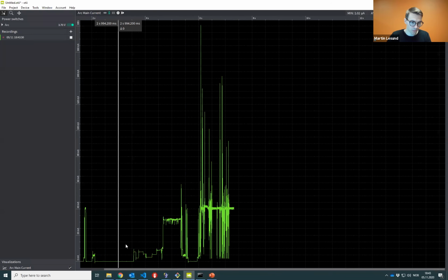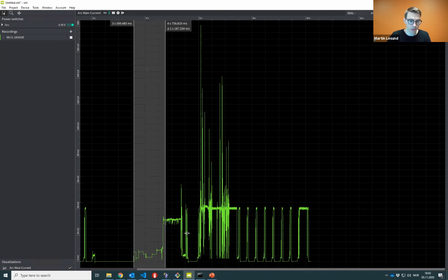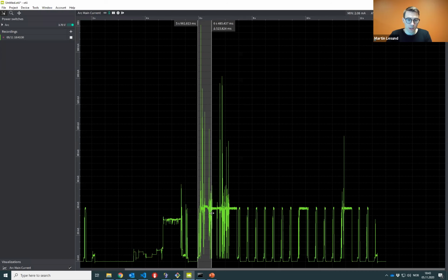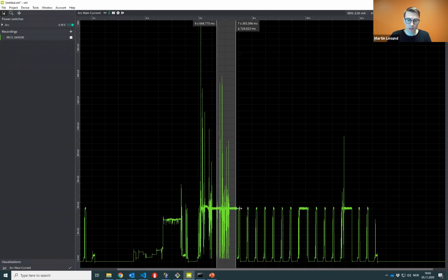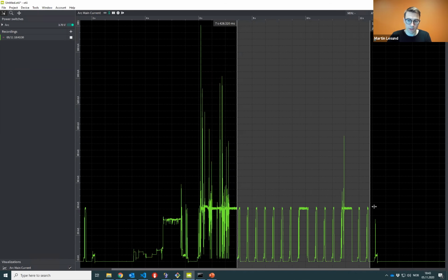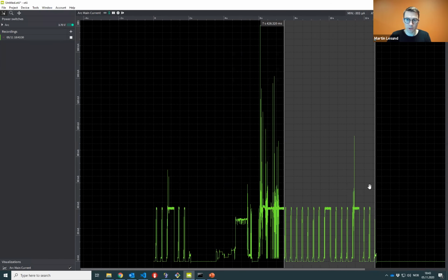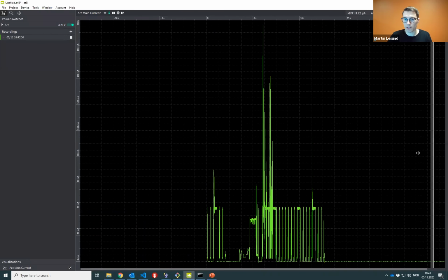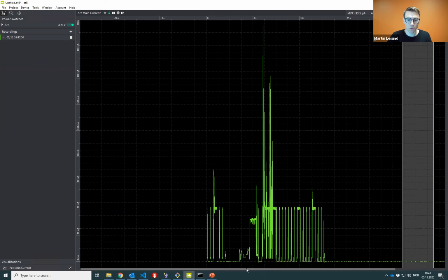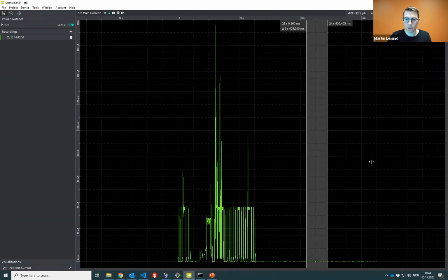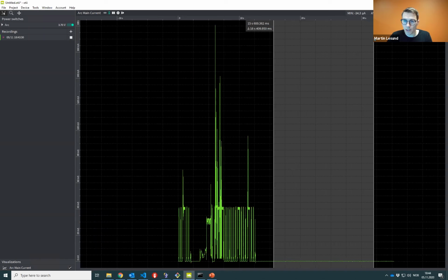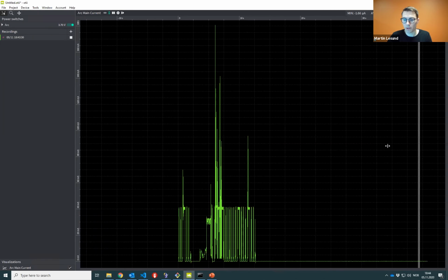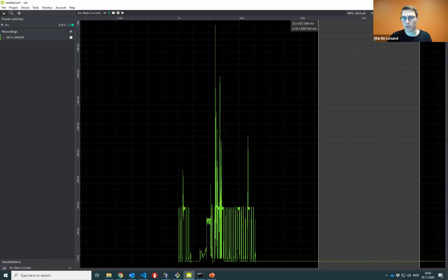So again, we restart here. We do the network sync, attach to the network, send the data, and then we are still in connected mode in the RRC inactivity timer for around 6 seconds, and then go directly to sleep. So I said that we have around 2.7 microamps floor current. And this is showcased up here. We can see the average is 2.57, so it's actually lower than in our specification. So these are quite good numbers we're seeing here.